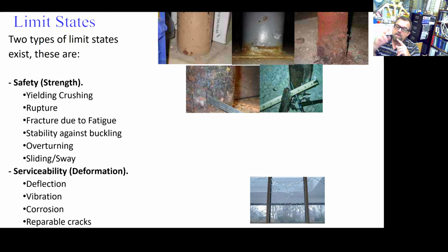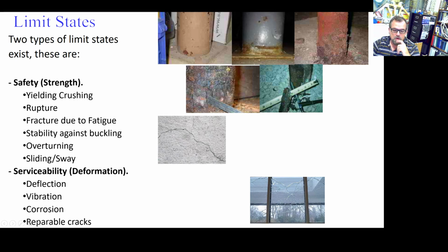Now, if you have transverse cracks in a reinforced concrete beam, what does that mean? Well, the concrete is always cracked, depending on the magnitude of those cracks, but usually those cracks relate to bending of the section. Is the bending too much? Is the confinement being lost? I don't know, but it depends on the type of cracks. So if you see a wall like that and you see that crack, that probably is nothing. Now if left unattended, water can start penetrating, going into that and creating more damage.